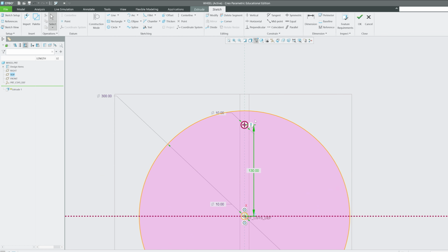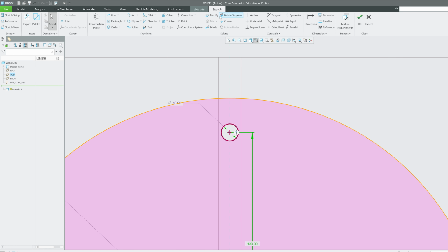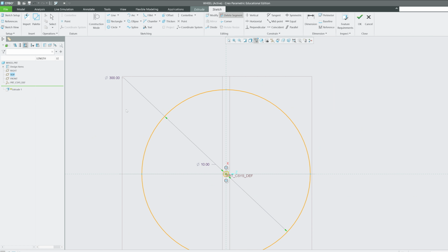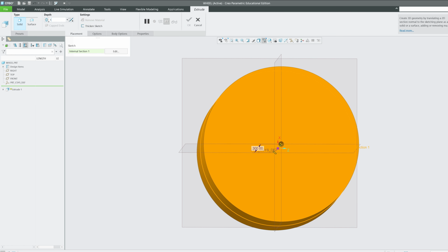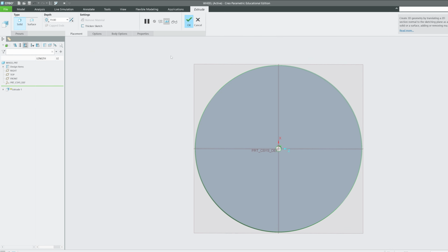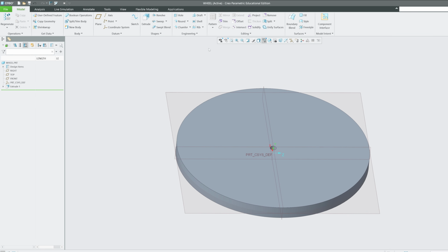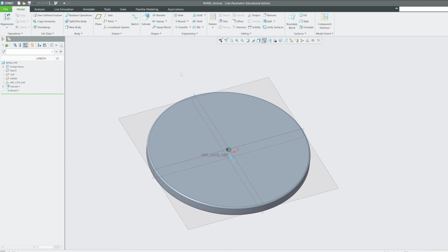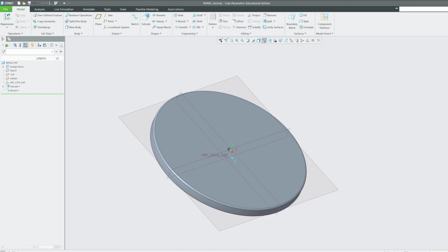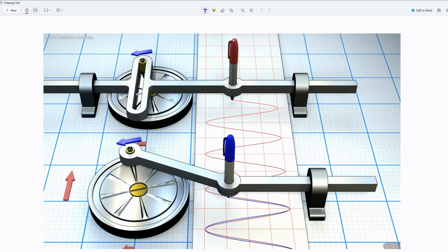Maybe I need to remove this because this one needs to be threaded probably. Yeah. So let's delete this one. Let's focus on these two. Now, let's click OK. Now this needs to be 19.5, or maybe I can make it 19.8 because 20 mm is the gap that we have provided. Now let's add something here. For example, I'm gonna add round. Let's make it 3 mm. I'm gonna select this edge as well as this edge. Now just to improve look and feel, we can also add things the way we have seen in this picture like this.